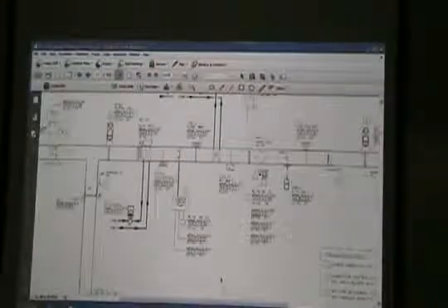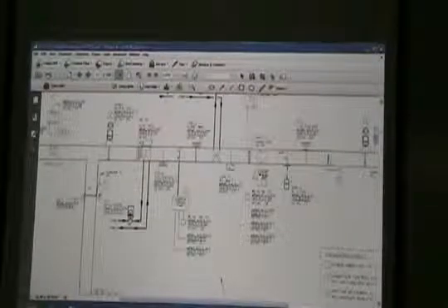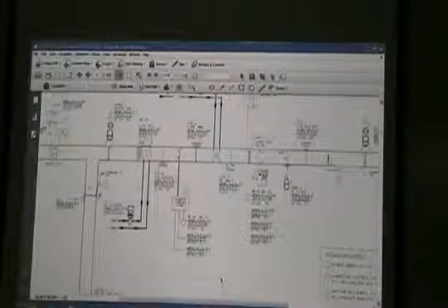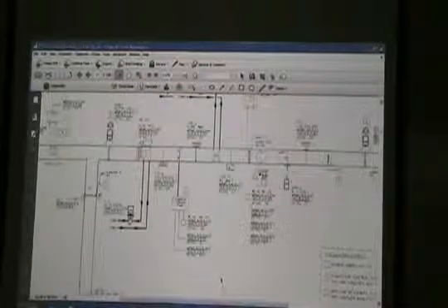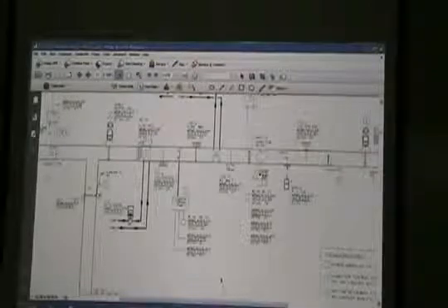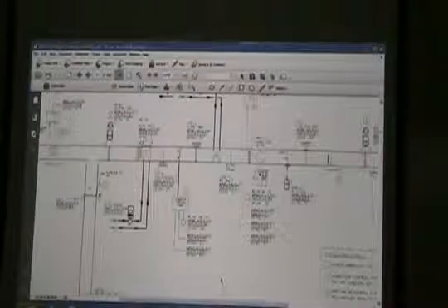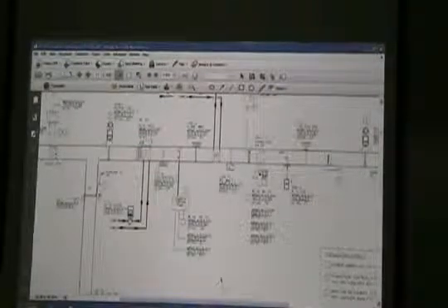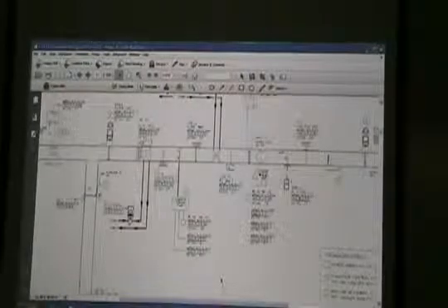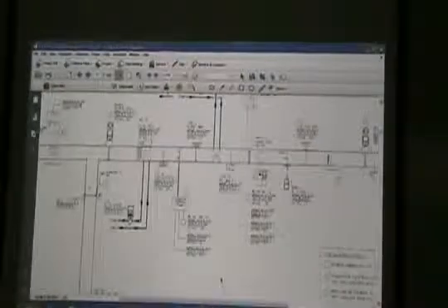So the preheat control valves will be modulated in sequence with a chilled water valve to maintain supply air temperature at a set point when the mixed air temperature is above 40 degrees. So mixed air temperature, I guess, is that one? We got it after the preheat coil. That's not right. Because of the preheat coil, you're going to have constant fighting back and forth right there.